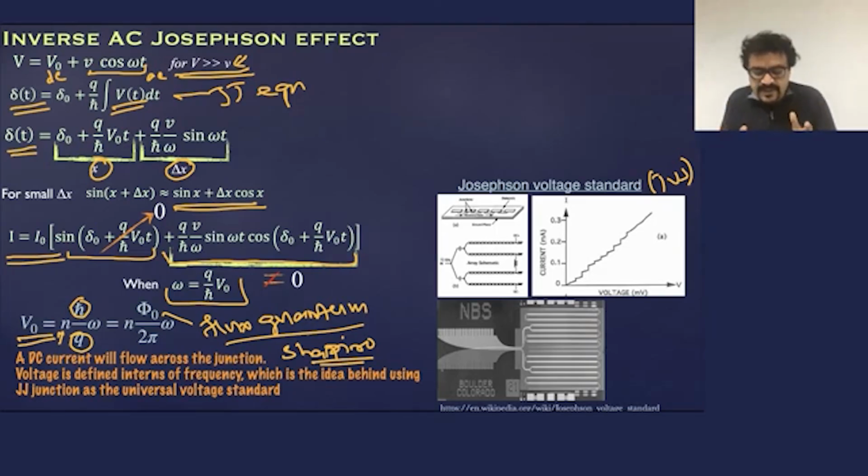But the point here is that this phenomenon, the inverse AC Josephson effect, is the main workhorse behind the Josephson voltage standard. It's one of the quantum metrology standards.